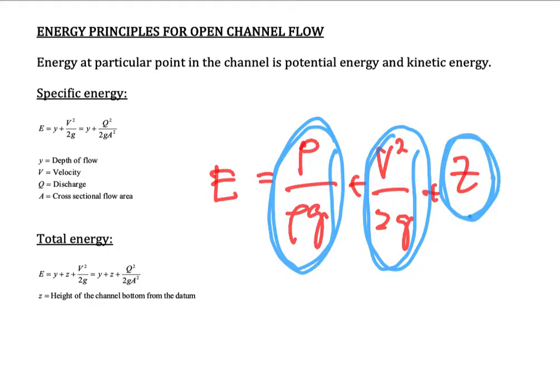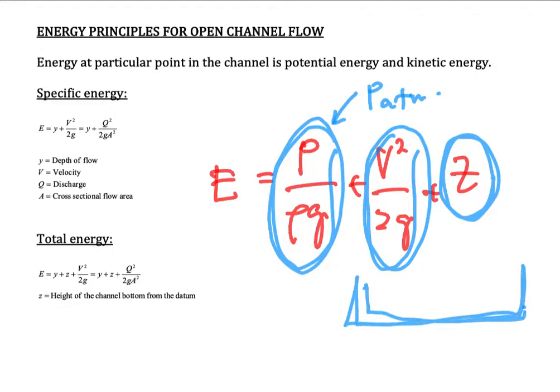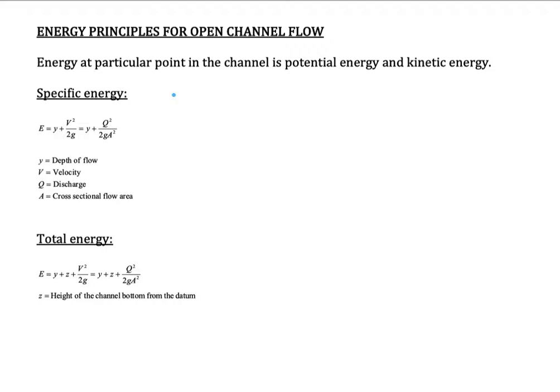Okay, the same goes for open channel flow. By right, we could still apply the Bernoulli equation. However, because the pressure is always P atm, the Bernoulli equation that we apply in open channel flow just consists of kinetic and potential energy. So this is the first basic idea about energy in open channel. However, in open channel flow, we are not using the terms of the Bernoulli equation. We are using special terms called specific energy and total energy.